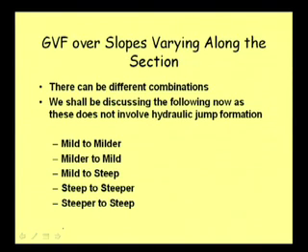Well, now with this understanding, we can go to another topic, that is gradually varied flow over a series of slopes. Series of slopes means varying slopes. Say a mild slope is there, then in nature it has changed to a steep slope, or maybe mild has changed to a milder slope, further flatter. So, that sort of combination is very common in nature, and rather in nature we will be getting this sort of combination only.